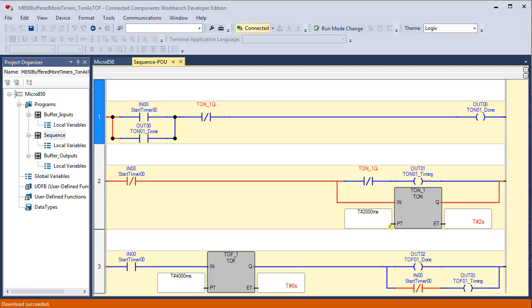The reason that we did that with RSLogix was because there was only one timer data type, and it supported or backed all timer instructions. And that data type had a done bit, and the done bit worked okay for on delay, saying that the interval was done. But in order for it to work correctly for a TOF, the done bit went on immediately and then went off after an elapsed time after the rung went false, delay off. That was a bit confusing.